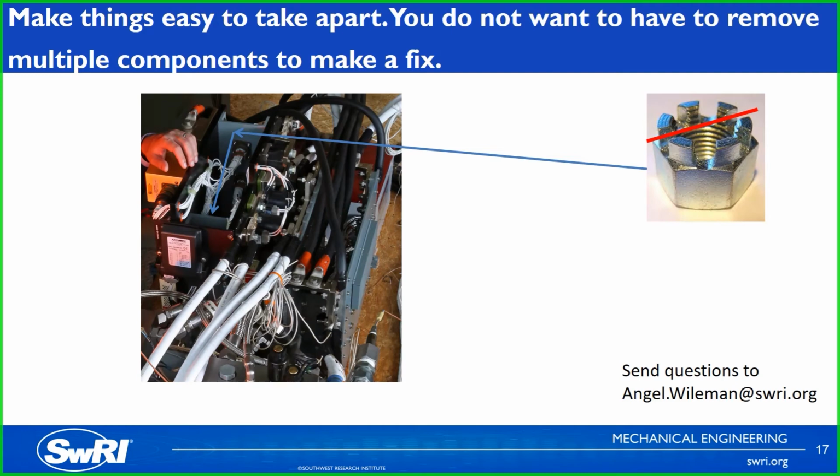So, doing things like temporarily having easier methods to take it apart that might be different. For example, we didn't have to have this all bolted together. We could have had it clamped together in the beginning until it was finished, and then once we were ready for sell-off, we could have put the nuts on. Trying to think through, is this easy to disassemble? Again, that can eliminate some of the time it takes as you go through the commissioning process.